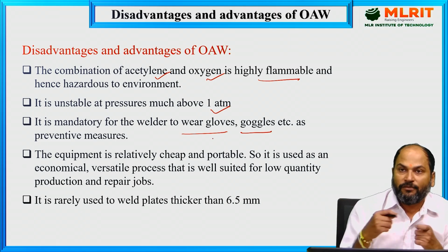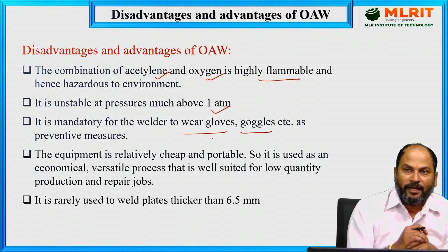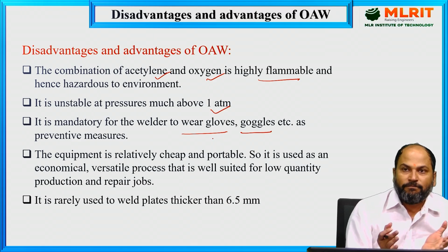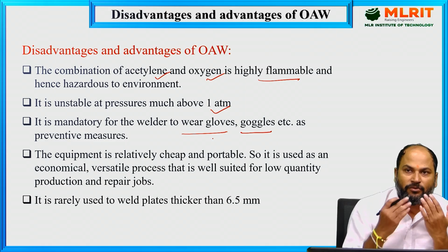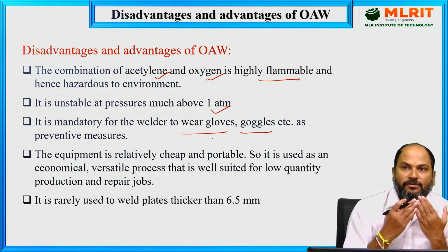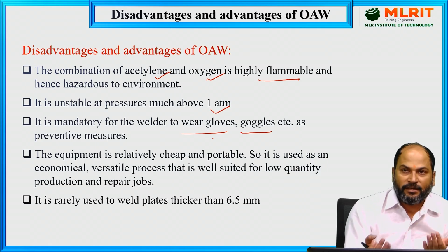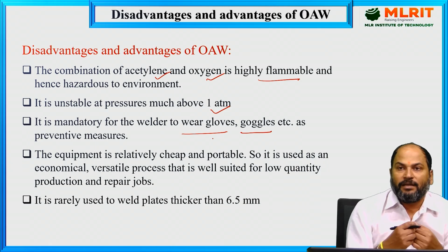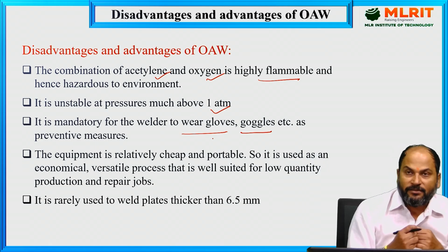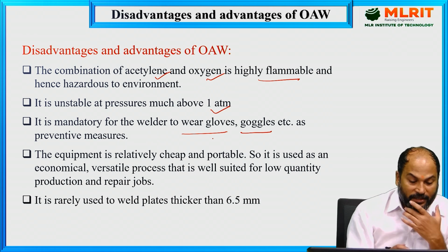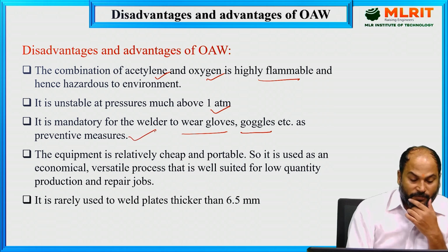Whoever is doing the welding, the welder or the technician, needs to cover his hands, cover his eyes, cover completely. He should wear a mask also so that whatever dangerous gases or fumes come out during the welding shouldn't be inhaled by the welder, because it will be very dangerous for his health. So these are the disadvantages of this process.